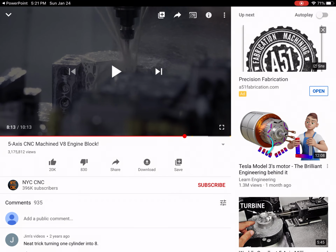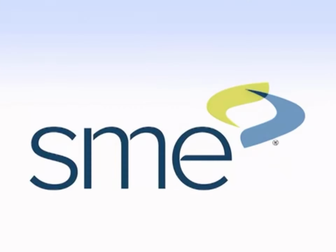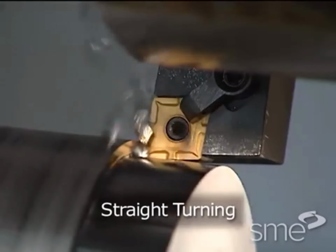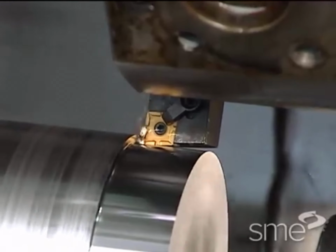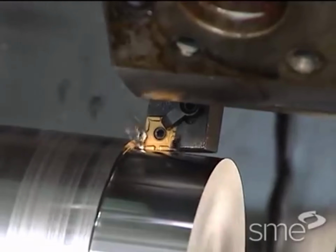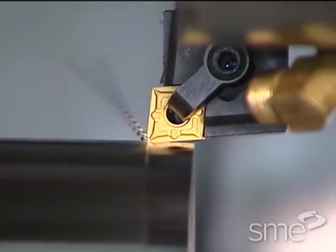Alright, so this is the first video, and now let's look at the rotational part coordinate system. We're going to use a turning operation to demonstrate. In straight turning, the tool is fed parallel to the axis of the work to reduce its diameter so that the final diameter is the same at each end. Removing a significant amount of material in one pass is called rough turning. The final lighter cut that creates a smooth surface finish is called finish turning.